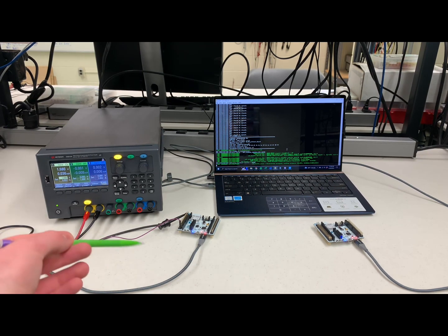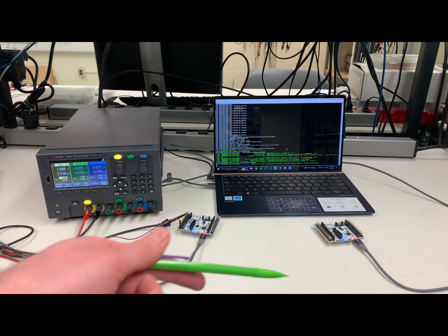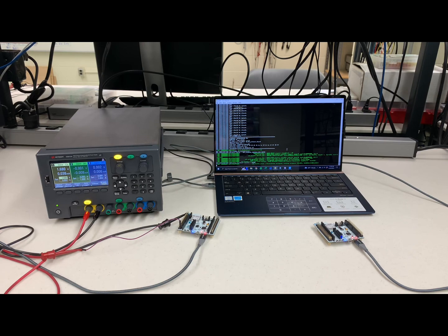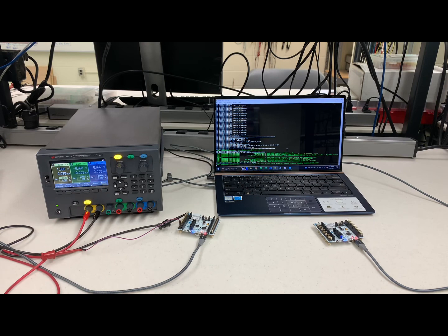On the left, we have a stand-in for the sensor unit, and on the right, we have a stand-in for the central hub unit. The sensor unit is getting a digital voltage that corresponds to a temperature sensor value. That gets converted via the ADC into a temperature, and it has two buttons, one of which sends the data to the central hub with a tag saying that the room is unoccupied, and the right sends it with an occupied tag.